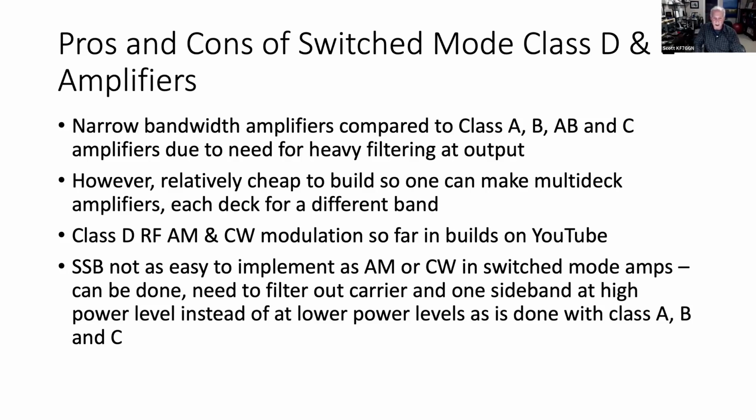It's only primarily AM. And they can be used for CW because if you're not using an amplified carrier, you can just turn the carrier on and off when you key down and key up for CW. But for AM, that's primarily where the money is right now for these kinds of amplifiers in ham radio. But nobody's built one commercially yet. These are experimental ones.